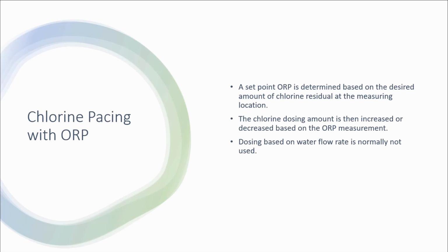So in the past, you were overdosing the chlorine to handle the variations through the day. Yep. So then you had to overdose your dechlor, sulfur, your dechlor, to make sure that you were covering that. So your chemical cost savings on both ranges. Yep. So that's good.